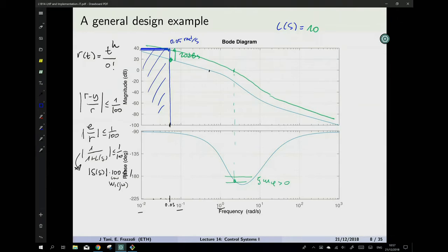So just by multiplying the whole thing by 10, by putting a positive gain there, the system is now unstable because of that ugly dip in frequency that it has, okay? So the specs require a margin of phase of at least 40 degrees. How are we gonna fix this?